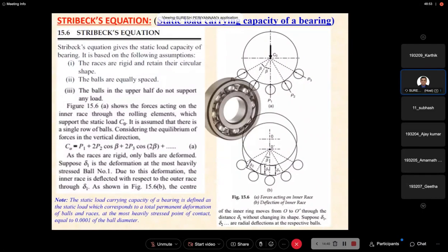Journal bearing is like boundary lubrication. Boundary lubrication, what example? IC engine, right? Then which one is more rigid, roller bearing or journal bearing? I give you a clue. Journal bearing, sir. Yes, because wherever there is more surface contact, the rigidity will be more, right?